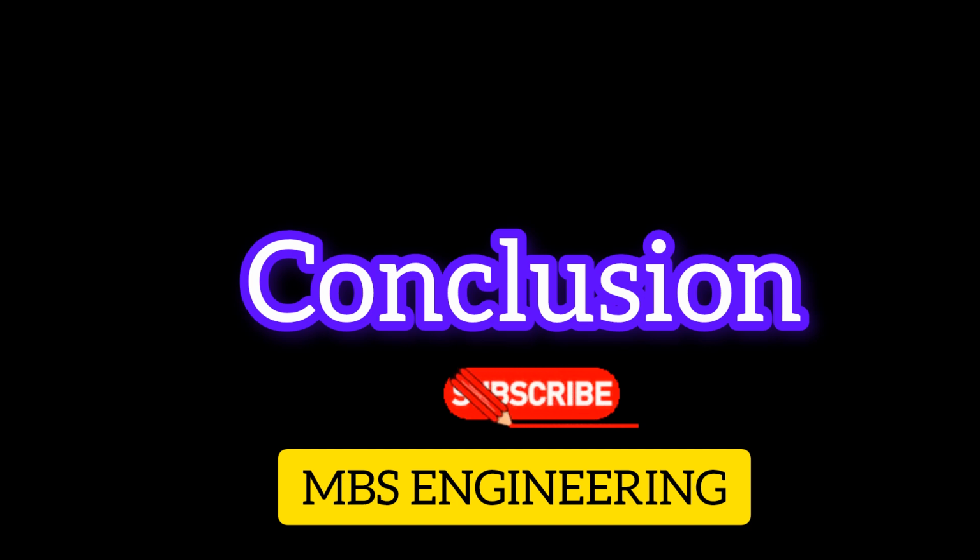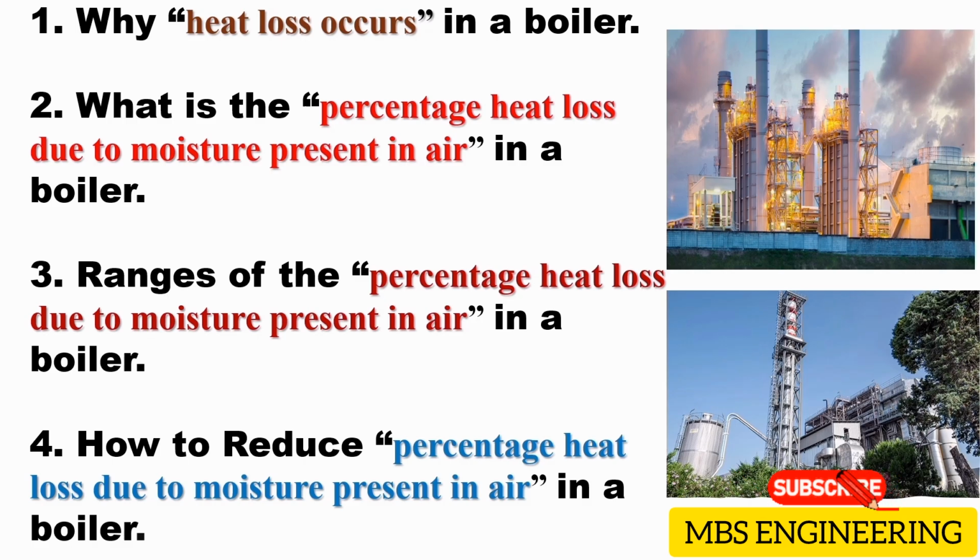Next, we summarize, and the conclusion of this video is: let's quickly recap what we learned. Heat loss due to moisture in combustion air occurs in three stages: sensible, latent, and superheat. And it can range from 0.2% to 1.5% depending on fuel and air conditions.